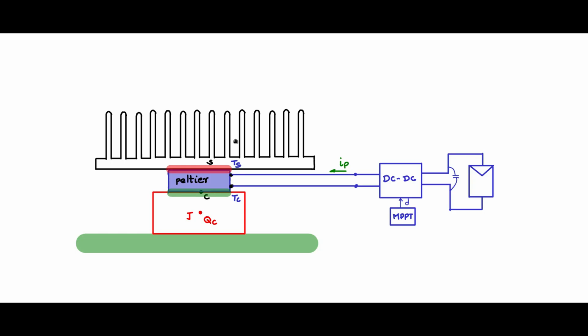It becomes very important now that the heat that is put into the heatsink should be removed at the rate that the Peltier junction is allowing the heat flow from the component to the sink. So this QC, rate of heat flow, should be maintained from the sink to the ambient.